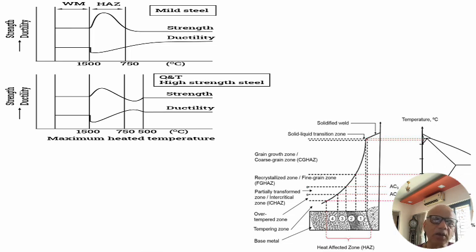But at the same time, since it is a metallic material, it has a coefficient of expansion and other associated properties, and if we are not able to take care of those properties and manage our heat, our cooling and our fixturing, then we cannot protect the parent metal and the weld. The heat affected zone is very thin, maybe from a few microns to 2, 3, 4, 5 millimeters, depending upon the thickness and the type of material and the material properties.